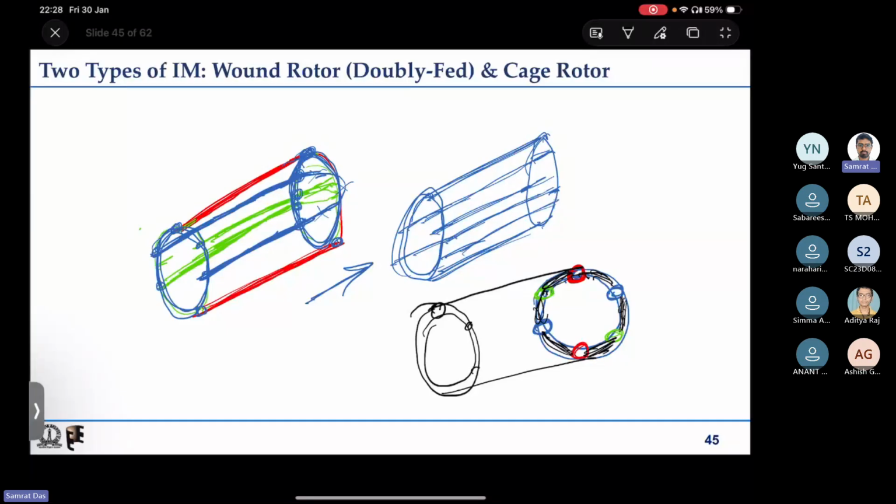So we can even do this, and the same thing will happen. We'll see what happens if we have this type of rotor, this is like a cage. So if we have a cage rotor, then what about the induced EMF in the bars, in these different bars? We'll look at that, and from there we'll try to understand the currents, because today even for the coiled case we did not look at the currents in the different phases. We just looked at the induced EMF.